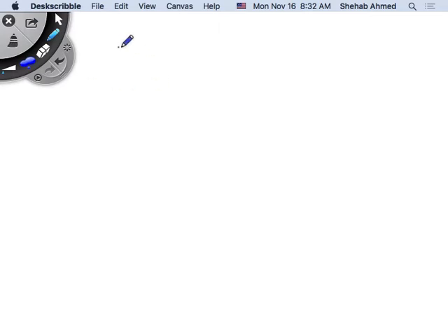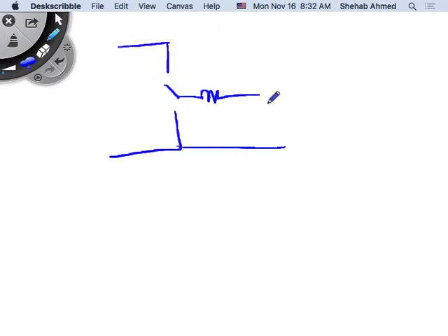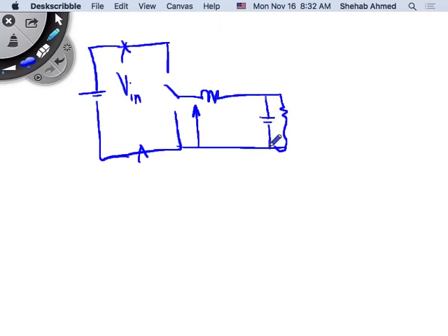So we said that all our circuits will behave very similarly, meaning I will have this voltage source, the input, and I will come up with an average version of it that will be seen here all the time, regardless of the topology of the circuit. In this case, it's a buck converter, and this will be dependent on duty ratio. It's dependent on the voltage between these two terminals and the duty ratio, right?